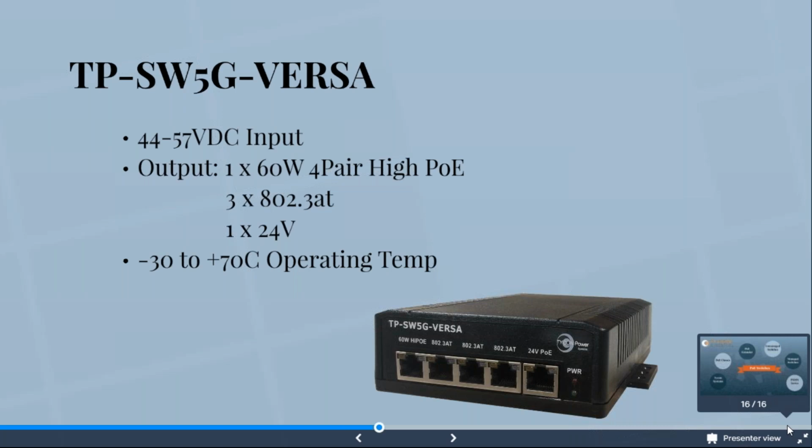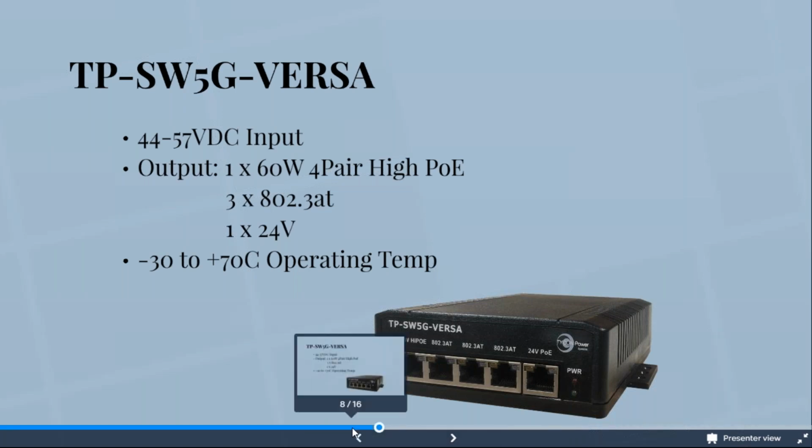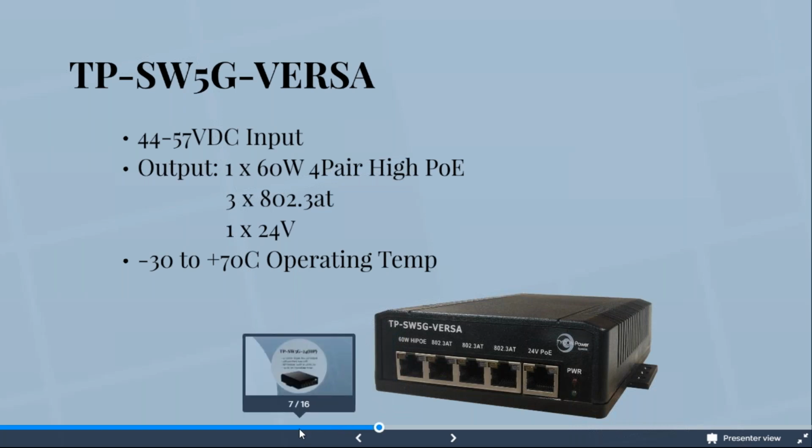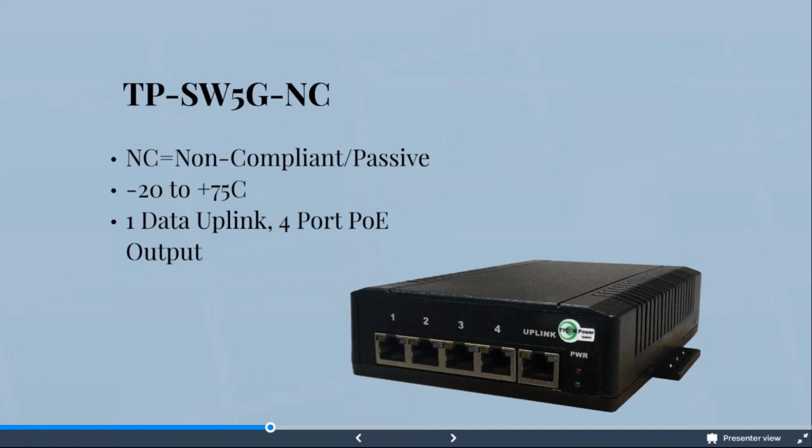So for example, you're not going to see a lot of devices that require 12 volt PoE. I haven't seen anything in probably 10 years. We do still see some 18 volt PoE, but it's really hard to find an 18 volt power supply to provide that. So most common is going to be your 24 volt passive. Passive just means it's passing through that voltage. So with our non-compliant switch, or our passive switch, what you provide will give you that voltage on all ports.